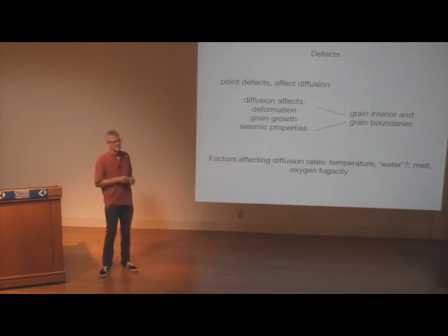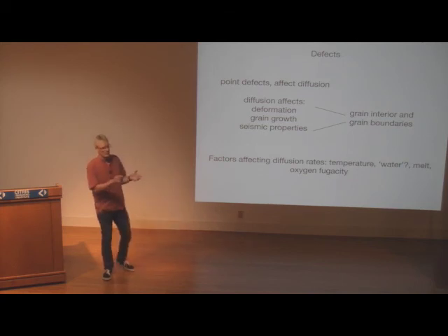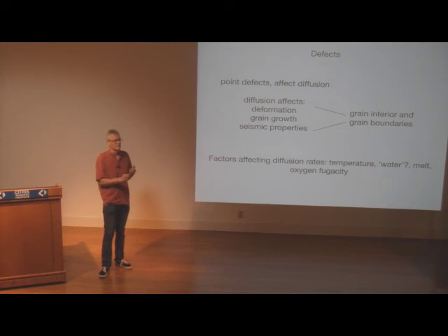So how can you isolate then the temperature dependence? Then I guess you need to adjust for that after the fact, like what Kornaga did, for example. You can explore the sensitivity, because you fit the temperature dependence, you fit the stress exponent, that prefactor A, you fit that all at the same time. So if you have enough data, then you can explore the codependence and see what your best values for each of these parameters is.